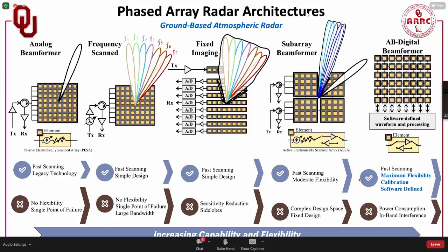With older architectures, we would use analog beamformers. This older approach is simpler to implement, but it comes at a cost. It costs flexibility and capability. Now, with recent developments in the wireless communication industry, we are able to bring digitization as close as possible and work at each radiating element level, which basically leads us to a software-defined radar.